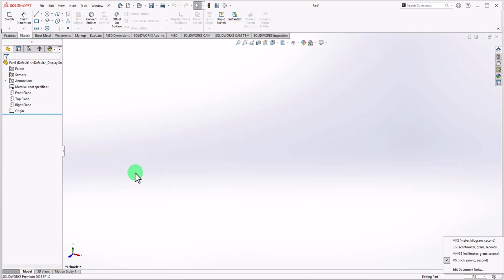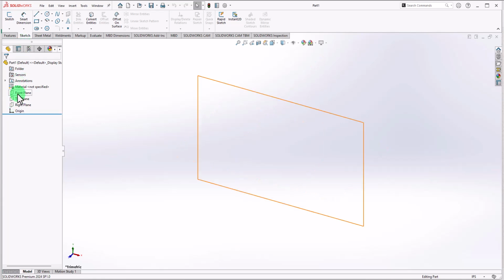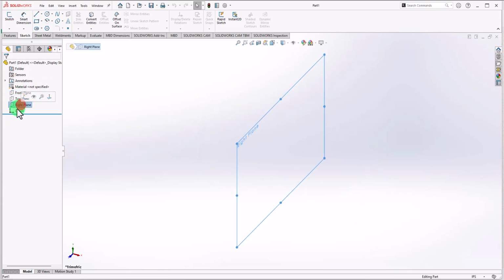So starting with SolidWorks, there are two parts. One is called the sketch based feature, and the other is called the solid feature. For the solid feature body, you first create a sketch. In the sketch bar we have multiple options. For activating a sketch, you have three planes here: front plane, top plane and right plane. These planes are perpendicular to each other.